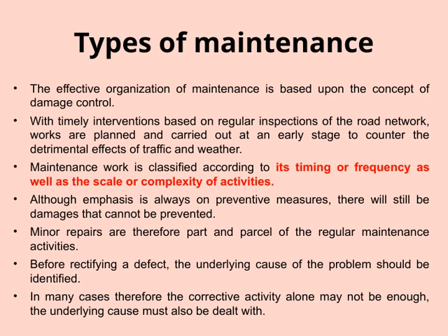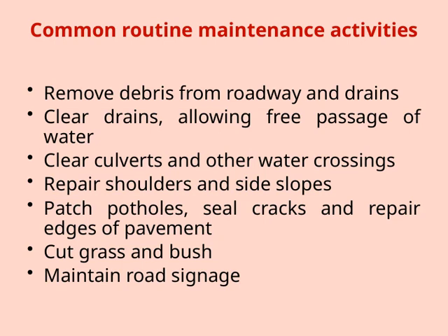This approach helps ensure that maintenance isn't just reactive, but proactive, aligning with our goal of sustaining a safe and durable road network over time. Now, let's talk about some common routine maintenance activities that are essential for keeping our roads in good shape. First, removing debris from the roadway and drains is crucial because it prevents blockages that can cause water to pool or lead to deterioration.